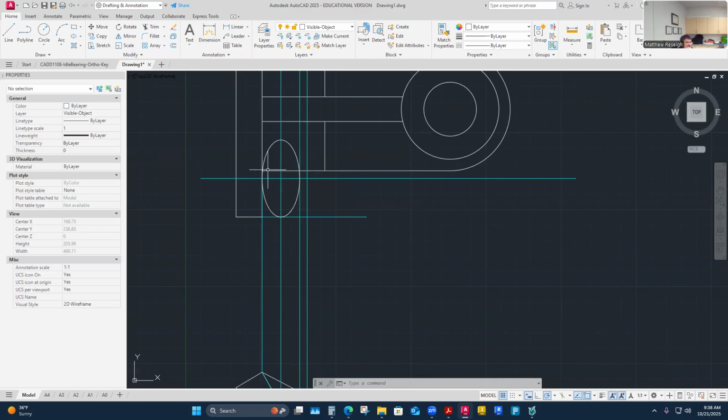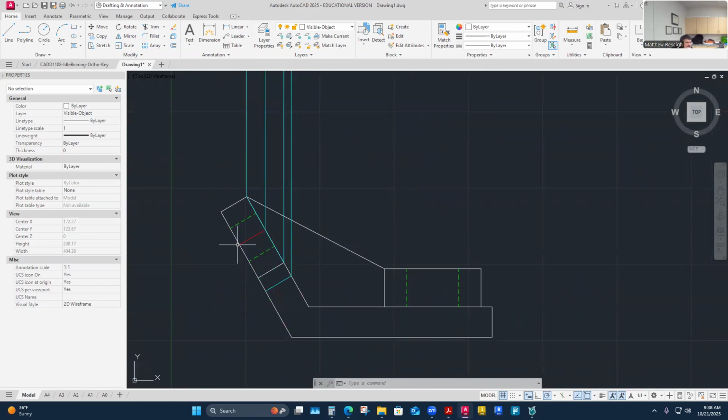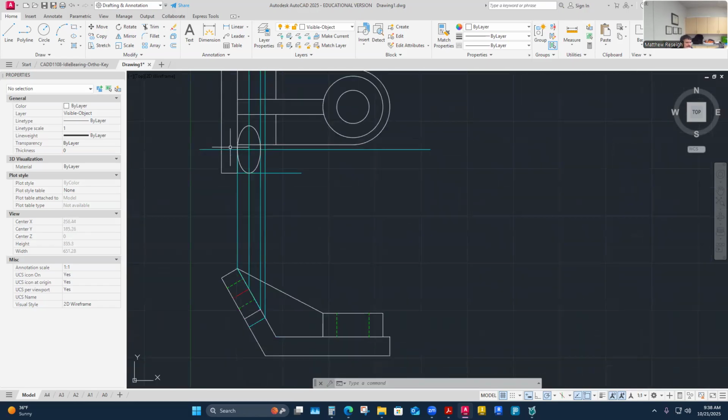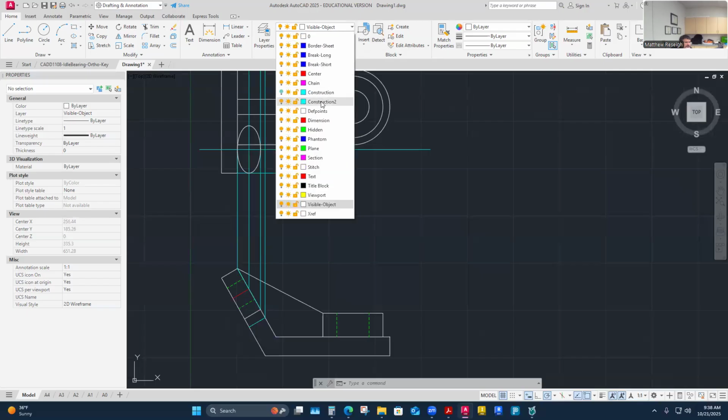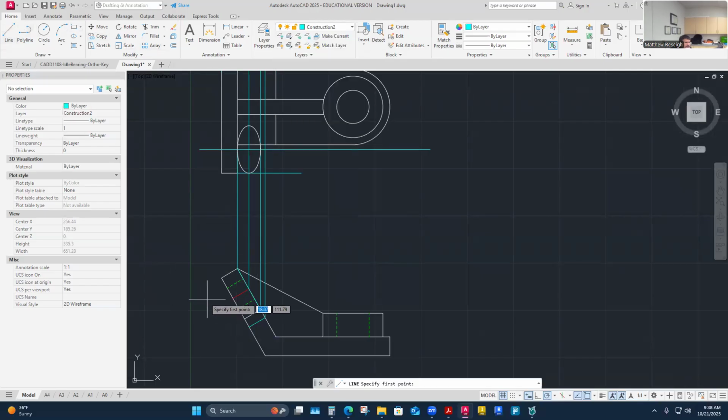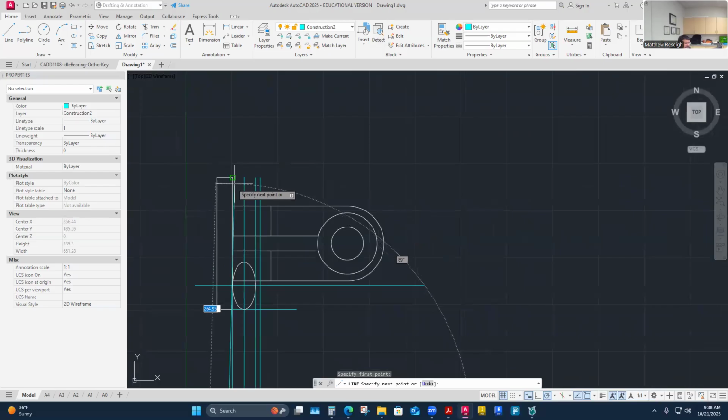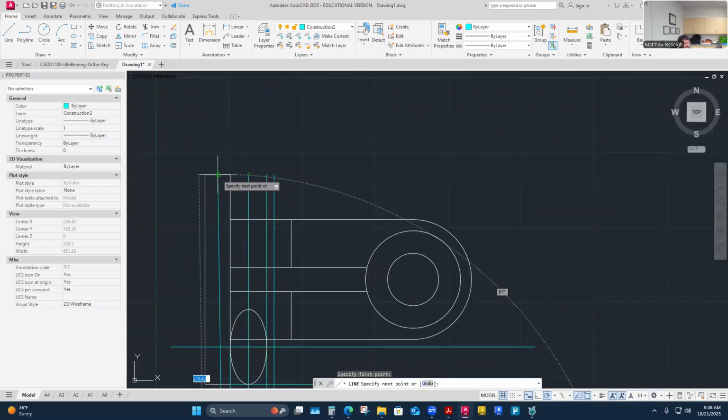I can't see it, but what I'm going to do is project this center line up to here, because this is all based off of this center line. Now I'm going to project this center line up, and I'm going to be able to copy this over to that center line. All I have to do is make one more projection from where the center line exits the thickness of the material here, right? This is what I need to know, where it exits. Maybe I'll pull this one through here up to there.